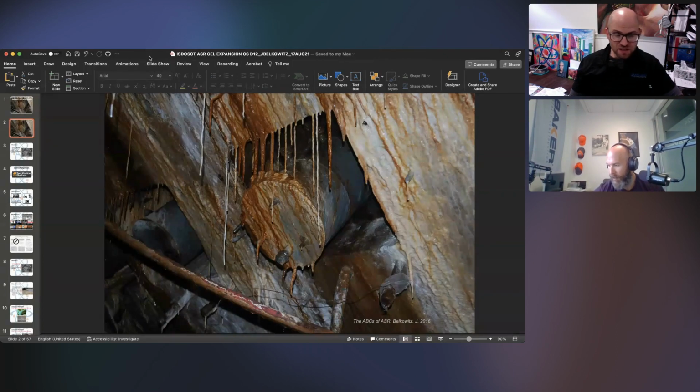Get the ebook, and it'll show you pictures like this, but this is ASR damage on a live structure in the United States. And what you see here is the after effects. Nobody cares about ASR until you start getting issues like this, where you see this gel-like stalactites, or is that mites? Anyway, stuff dripping out of the concrete, and that brown stuff is the steel corrosion that is caused by the failure inundated by the ASR.